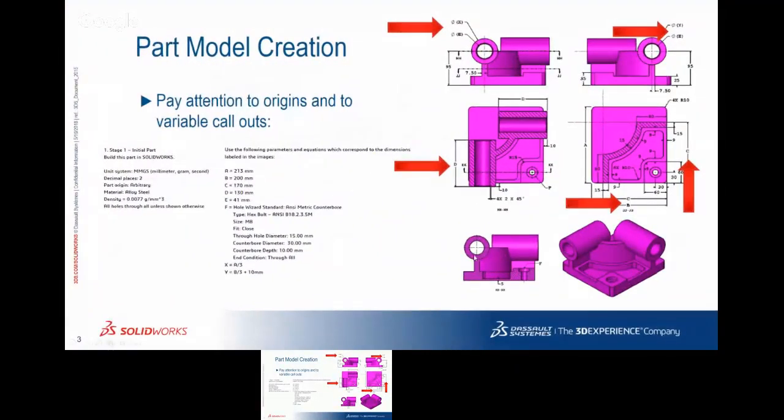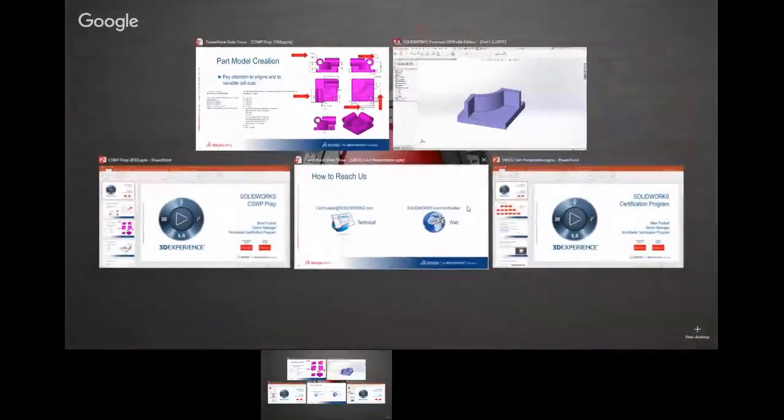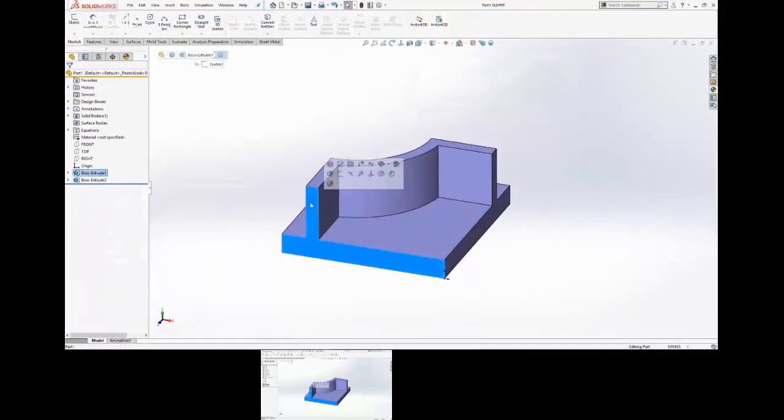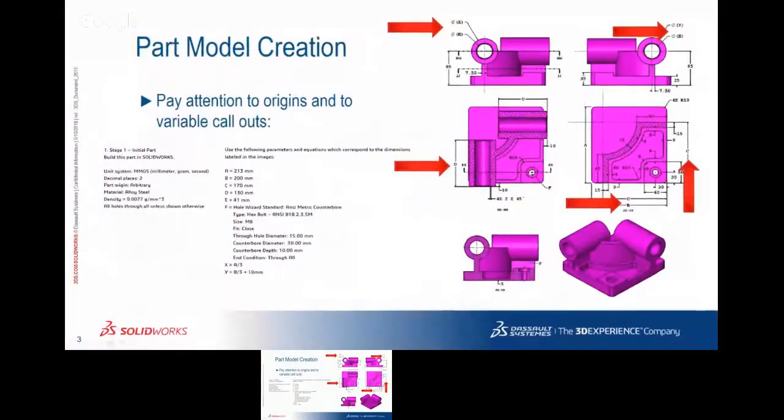Okay, so that gives us that vertical wall. The next thing I want to work on are these bosses. All right, these little bosses that are sticking out there, and then we'll work on this cutout down there. So I'm going to sketch on this face. And if we look at the part, there's a couple things. They are on the edge or the midpoint of what that boss is right now, that vertical wall. Obviously, we're going to cut a piece of it away, but that's where it is. So that gives us the midpoint of that little part that's standing up, the perfect spot to sketch these.